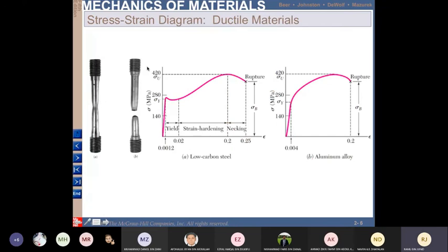And when you do the stress strain test, this is what you will get lah. This is stress, and this is strain. Okay, it is written like this. So when it fails, it can fail like this, and this is what it will exhibit. So this is the elastic region. And then passing the yield point, this is yield point.